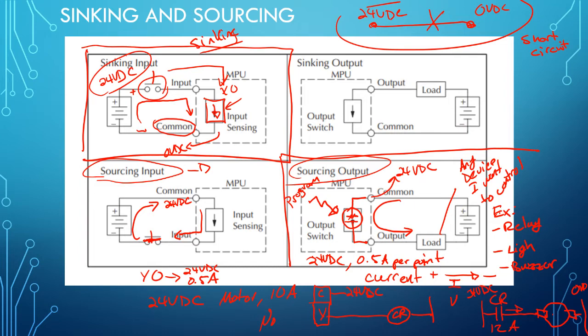But there'll be some questions regarding this and syncing output. So I don't think we discussed the syncing output. The syncing output, basically, you're connecting 0 volts DC to your common, and the PLC would take the current from the device. Let's say this is a control relay with 24 volts on the other side. Basically 24 volts over here, and over here you put 0 volts. So the current goes from here and syncs it to the PLC.